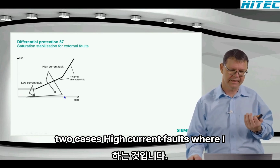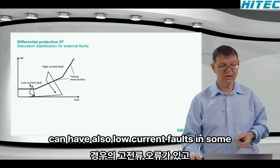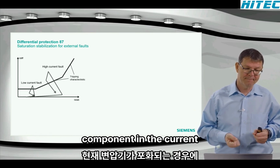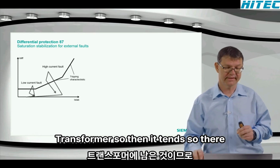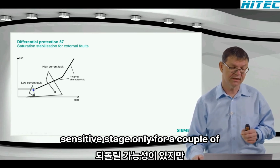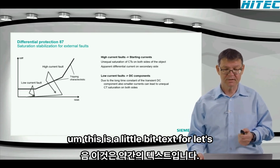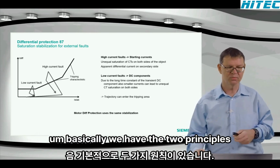We have two cases: high current faults, where I have CT saturation relatively fast, and also low current faults in some cases when the current transformer saturates because there's a lot of DC component in the current. And maybe again remnants in the current transformer, so there might be the possibility that it jumps up just over that relatively sensitive stage, only for a couple of samples and turns back, but this is enough to issue the tripping command. Therefore, two principles. This is a little bit of text for the documentation to read if you like. Basically, we have the two principles.